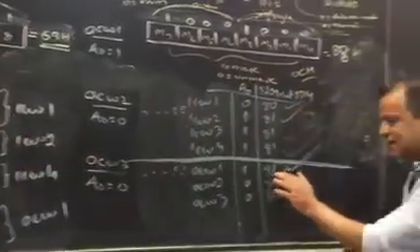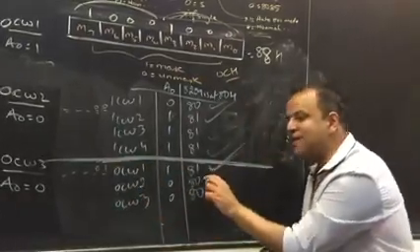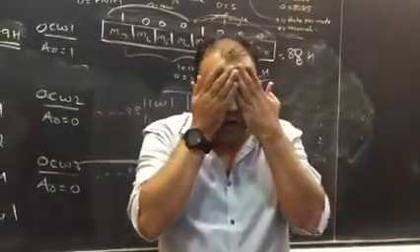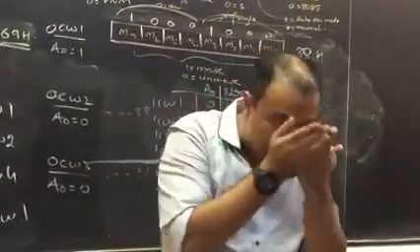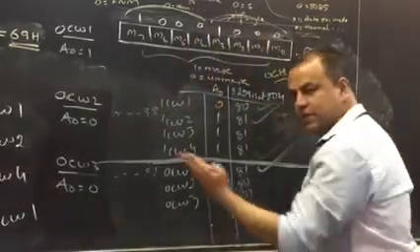A command coming at the address 81 is simply OCW1. A command coming at the address 80, before understanding whether it's OCW2 or OCW3, the 8259 will look at the command. We'll look at the fourth and the fifth bit, starting from this side, from the MSB, the fourth and the fifth bit.